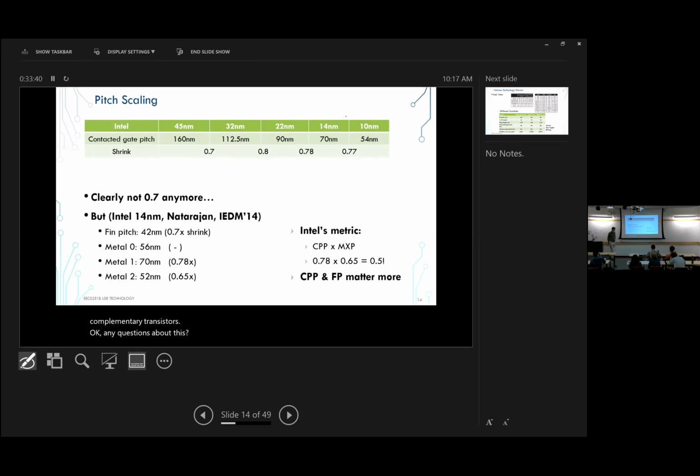Yes. So this thing is designed by this over again, like not scaling. They're not scaling it because we could not scale transistor thresholds anymore, because the source-drain leakage was getting to be too high. And as a result, because we care about performance, we could not scale the supply voltage. As a result, power density stopped being constant until it started going up.